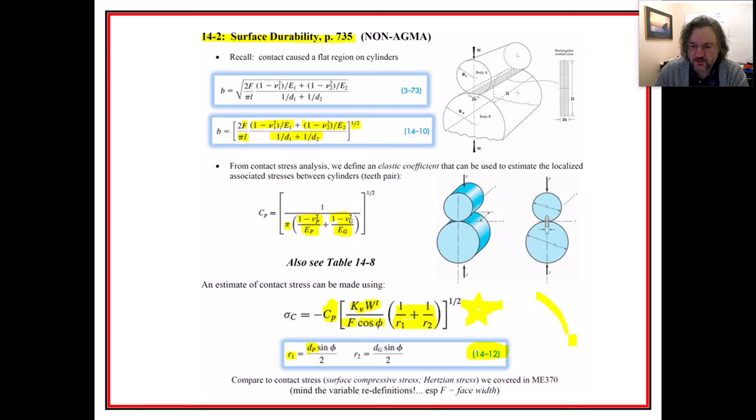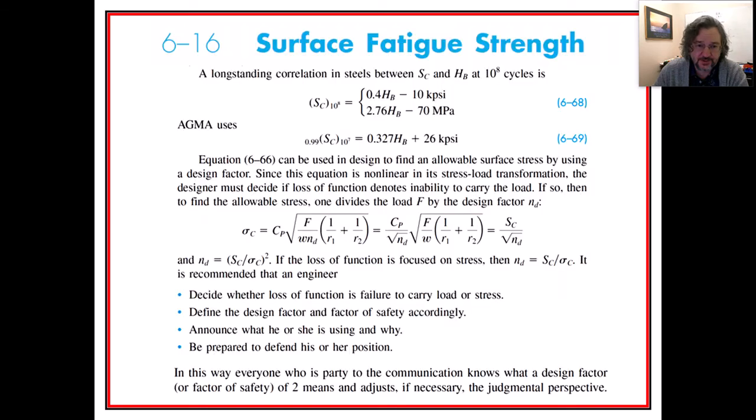That gear tooth, we know, is going to have this involute shape, and so to make a rough estimate of the localized curvature right there, we're giving a radius. That's what we're saying that radius is right there. We don't actually have that curvature for sure, but this is an estimate of it. So it's a good idea to compare these two things, figure out where all of them are coming from, and also see where the sequence is.